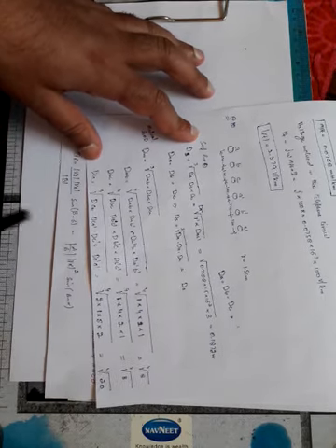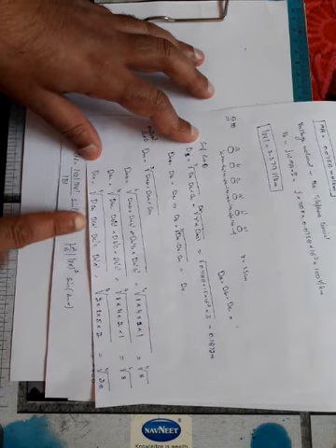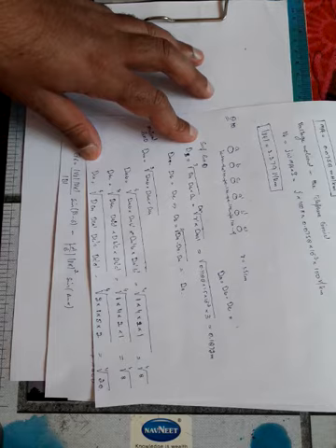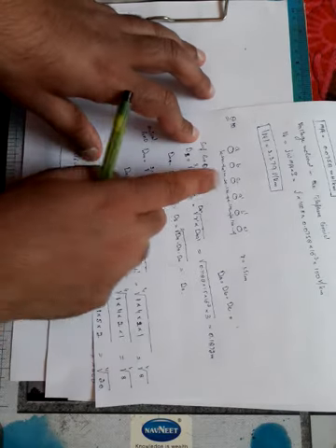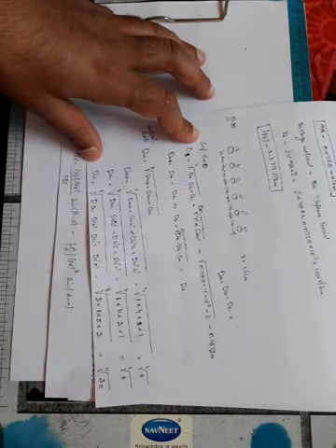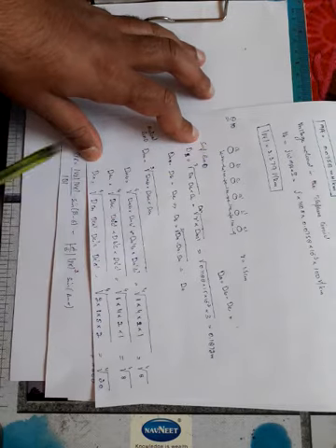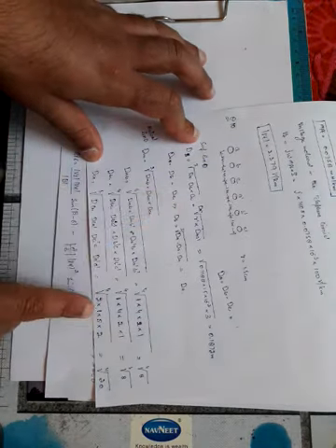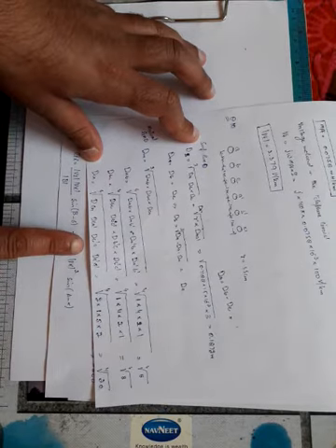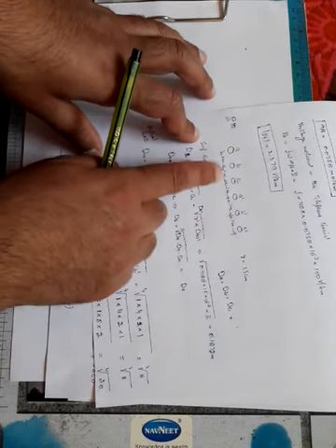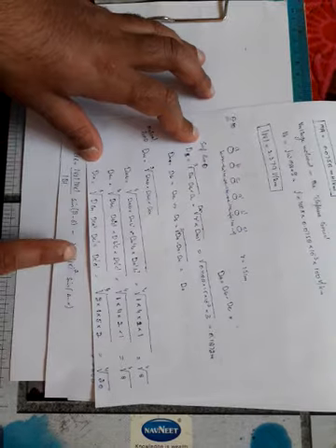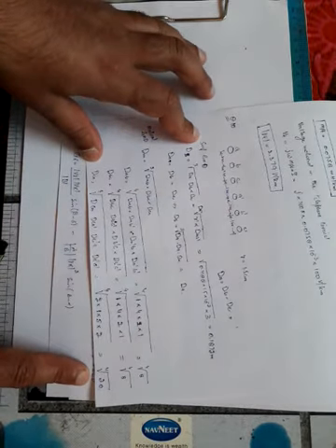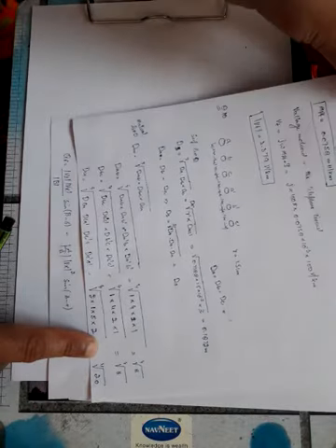Now DCA will be equal to DCA into DCA dash into DC dash A into DC dash A dash. It will be equal to the 4th root of DCA. C and A, their distance is 2 meter. DCA dash, C dash is 1 meter, DC dash A, C dash A, 1, 2, 3, 4, 5 meter, and DC dash A dash is 2 meter. It comes out to be the 4th root of 20.